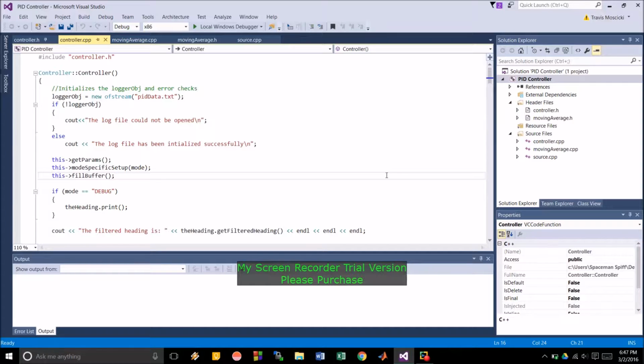That's really fast. Granted, you don't have anything to reference it to, but now check out the PI. The PI controller is going to rise a little more slowly and have some overshoot, but not as much, and it's going to oscillate a little bit, but then it's going to settle exactly on your desired state. That's a function of the integral term, which in the frequency domain is going to cancel with your error, and you're going to have zero error as the system time moves towards infinity.